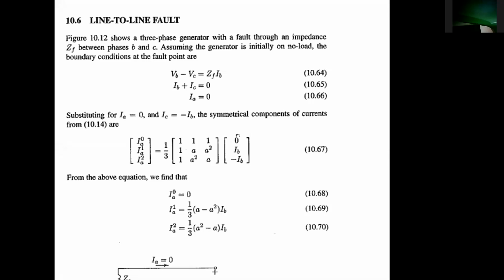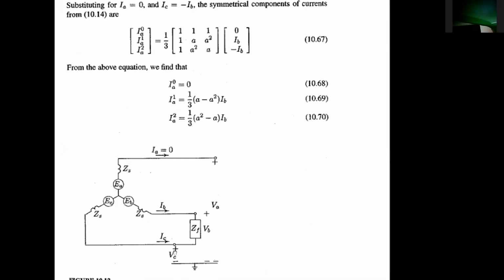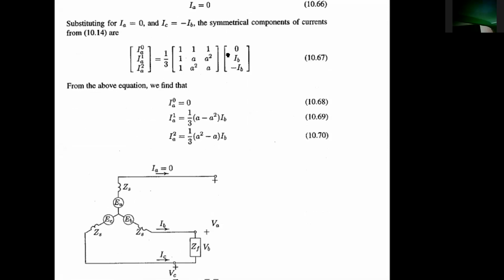And this ABC, how can we place there? First term is IA. You don't have any connection for that, right? Only short for second and third phase. Second and third phase have the short connection, but this is open. That's why you don't have any current. So IA will be 0, first term.